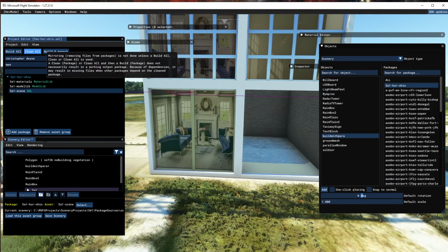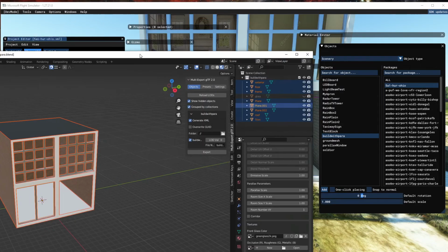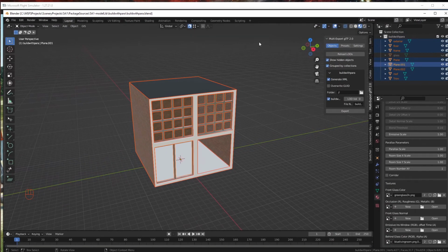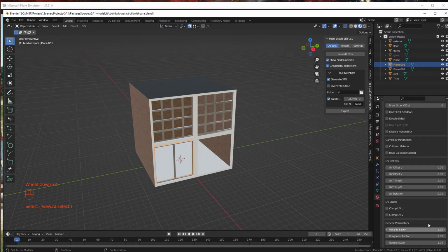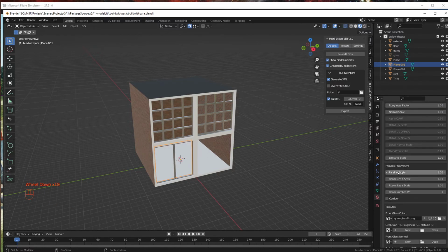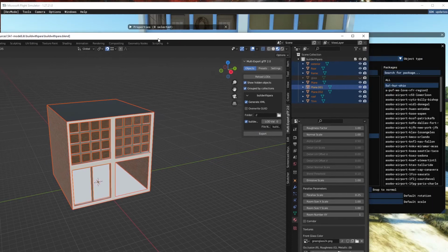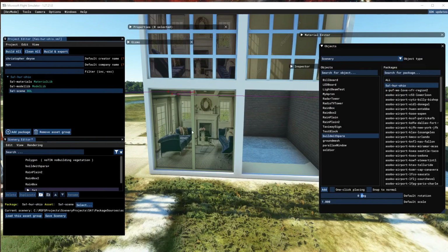Now, if I go back into Blender, and let's bring that back wall up further, closer to the window glass, which you probably wouldn't do. So in your Blender parameters, if I go to Parallax Scale and change this to, let's say, 0.25, do a save, and export again. Okay, now I'll have to update the GLTF again in order to have it live update.